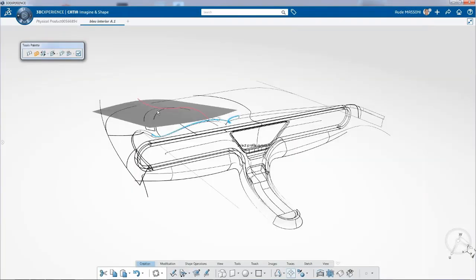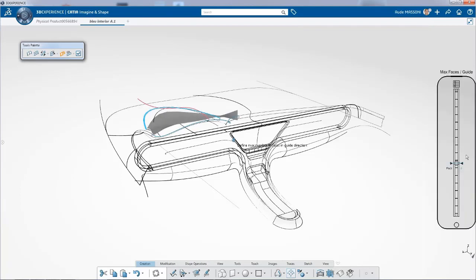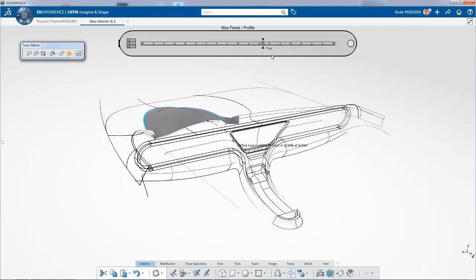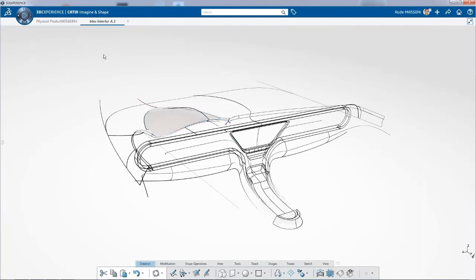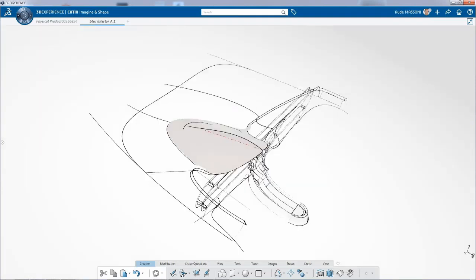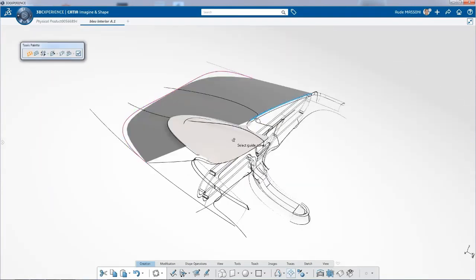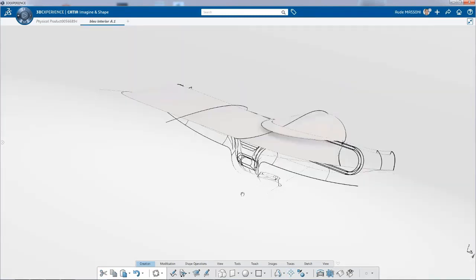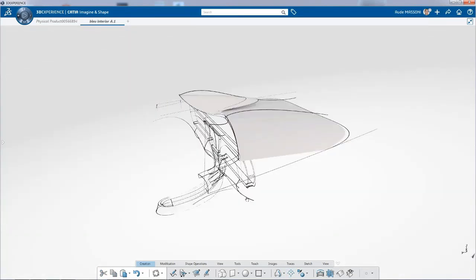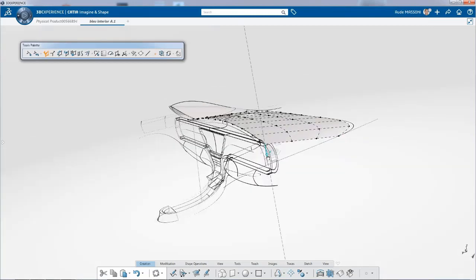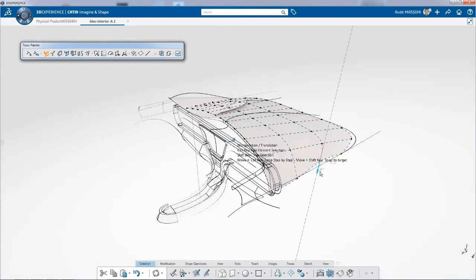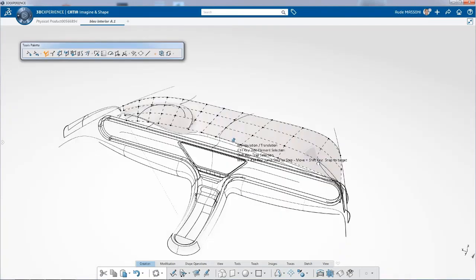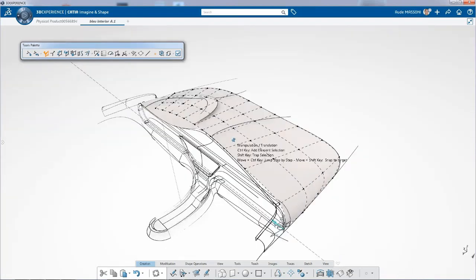And what we're going to do is, again, put a surface through 4 boundary curves, and then we increase the resolution to get it more accurate. You can see there's a slider bar here that increases the fidelity of that surface, so it kind of suctions to those curves. And at some point, we will let the 3D take over, and we can manipulate it, just pushing and pulling these control points of the subdivision surface.